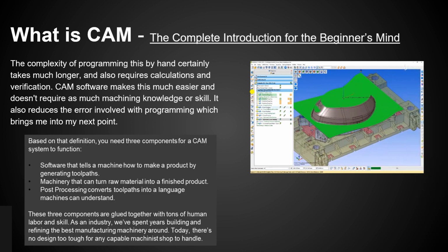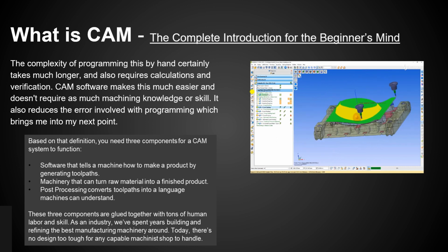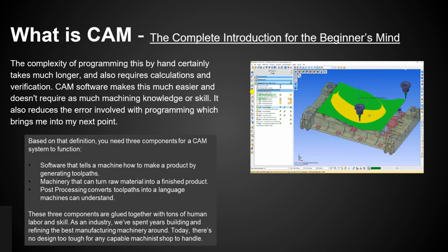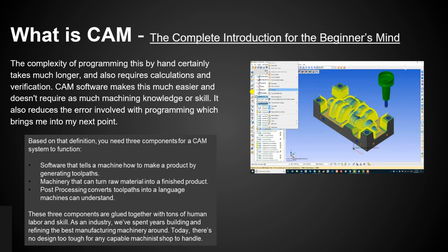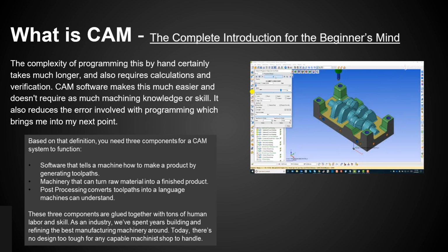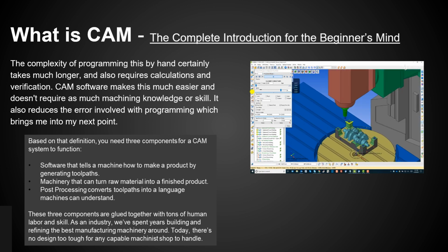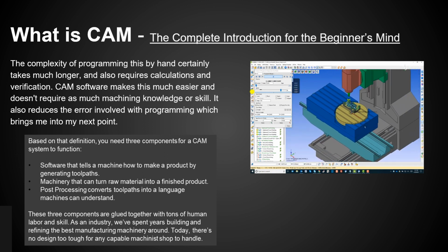The typical WorkNC customer manufactures plastic injection molds, stamping dies, 3D components, patterns, or anything with a complicated 3D shape. WorkNC is capable of 2D milling and drilling, and 3 plus 2 milling, along with 5 axis simultaneous milling, generating toolpaths along with G code and M code. WorkNC's interface allows the user to create reliable toolpaths with just a few clicks.